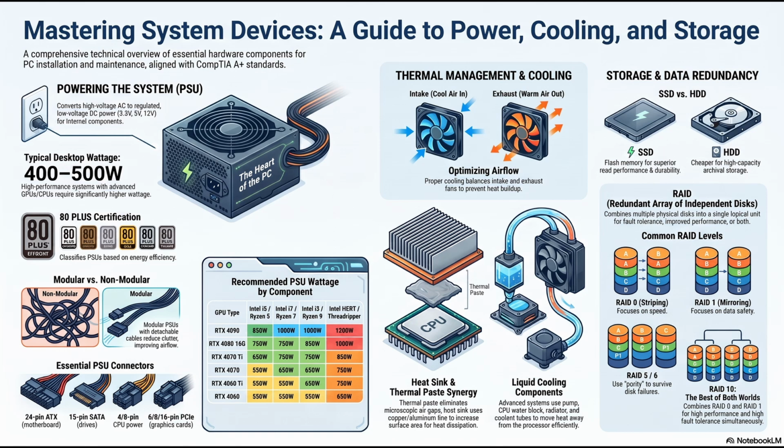Worst case scenario, that electrical surge bypasses the safety protections before they can trip, traveling down the cables and permanently incinerating your motherboard, your processor, and your graphics card. You've essentially detonated a small plasma bomb inside the case. Yes, you have. Note to self and to everyone listening: always verify the voltage, or better yet, just spend the extra $20 on an auto-switching unit. Highly recommended.